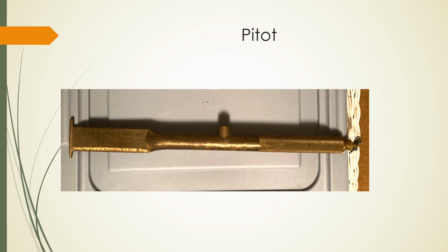So it's the reason there's so much variation in pitot pressures. When I look at someone doing a test, I'm looking at how they care for their gauges, whether or not they're calibrated, and I also look at the pitots that they're using, and I get a pretty good sense of just how accurate these numbers are going to be.